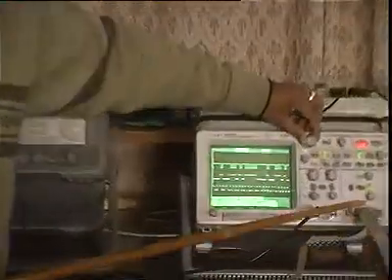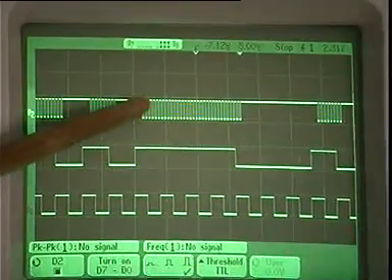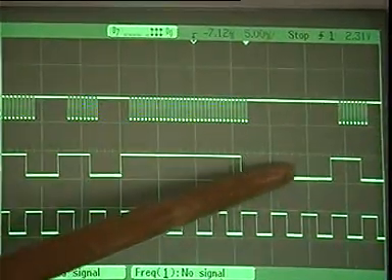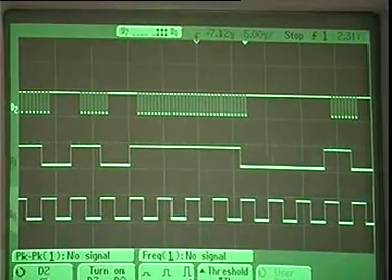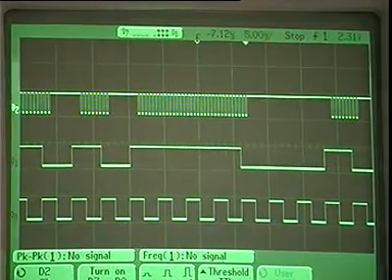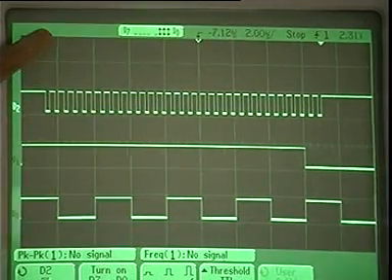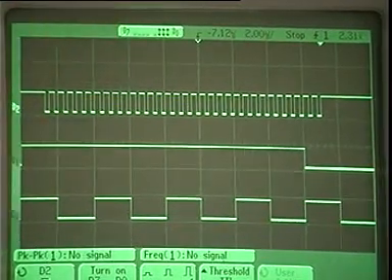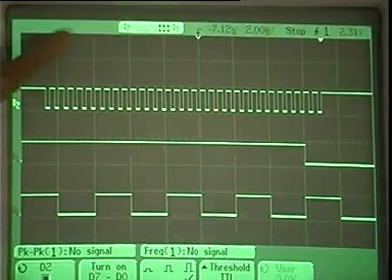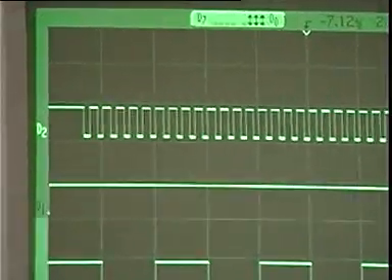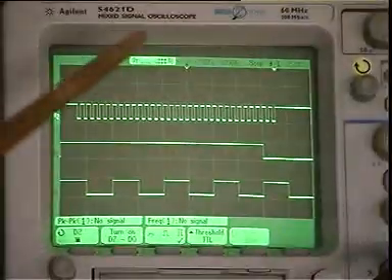So notice in this waveform, this is binary 1, so the carrier is transmitted. This is binary 0, there is no carrier. Again this binary 1, the carrier is transmitted. So this is amplitude shifting. One thing I want you to note here is that on the oscilloscope the carrier is appearing as if it's a square wave. In general, this is not correct. There is some clipping in the circuit because of which it is appearing as a square wave, but what I have used is a sinusoidal carrier. So this is actually a sinusoidal carrier with some clipping on it.